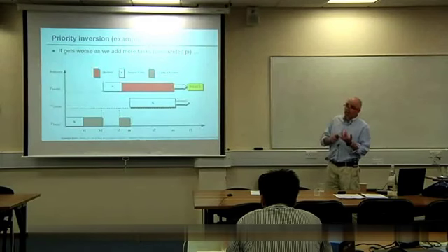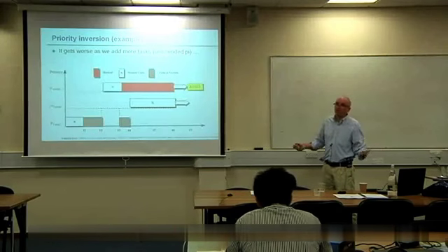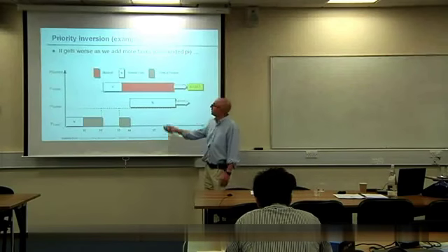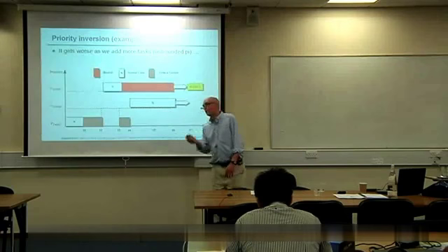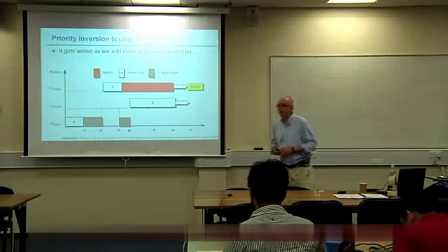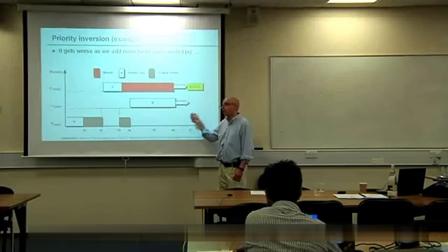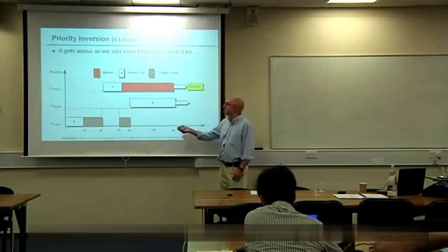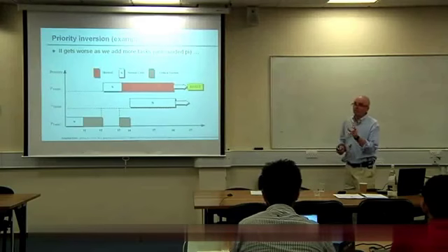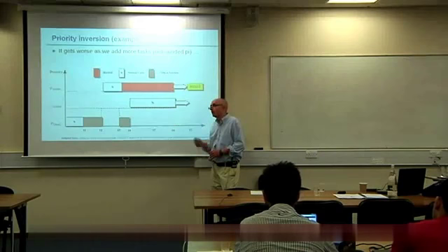So we put locking mechanisms in to avoid interrupting the ADC when it's halfway through its operation. We can deal with that. And we give the task priorities, but if we don't use some form of ceiling protocol to change the task priorities dynamically during the run, then we will get this scenario. So our option is to dynamically change the priorities during the run in a controlled way, which avoids this kind of scenario. But it's challenging.